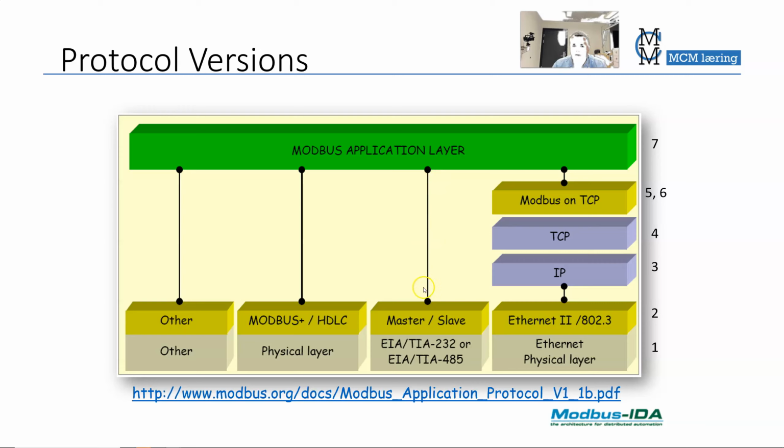because what's covered in layer 3 is global addressing. There is no global addressing in a small RS-485 network. There is no need for global addressing either. Layer 4 is how to divide a large message into small packages and so on. Layer 5 is how to establish a connection and free the resources when it's done and so on. So there are really things you don't need in order to communicate. Therefore, there is no need for such protocols. But you need something to give local addressing and to define the voltages and bit levels.